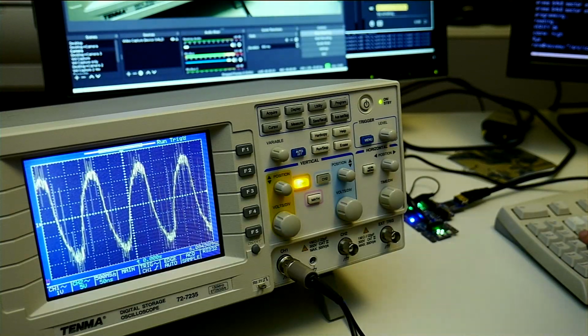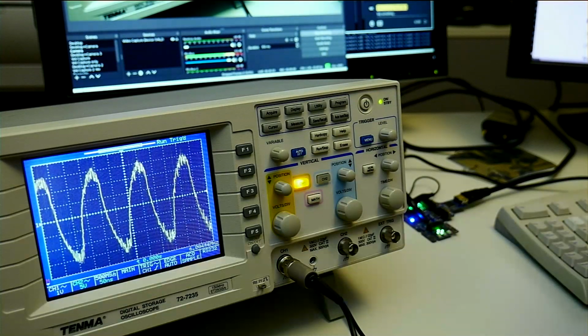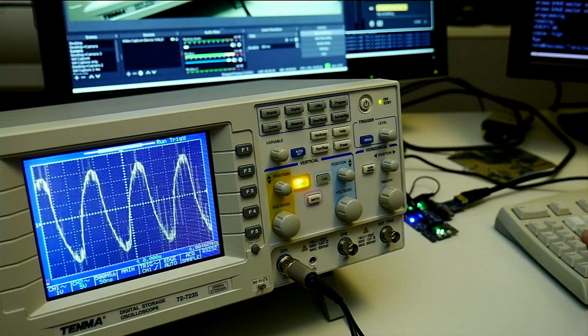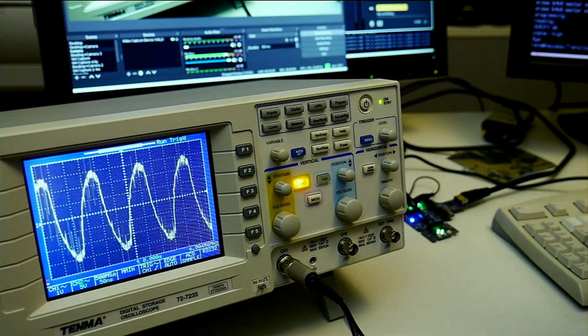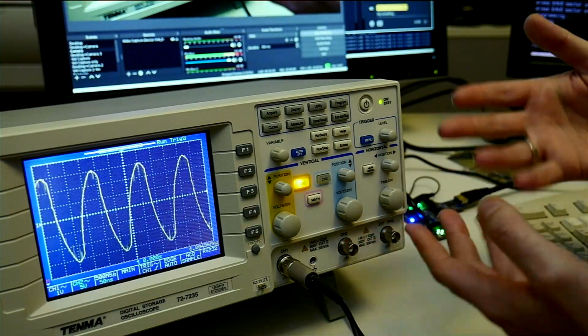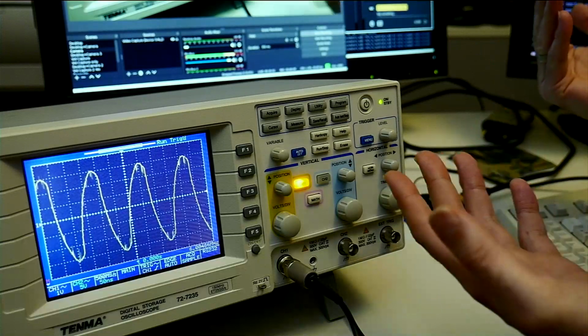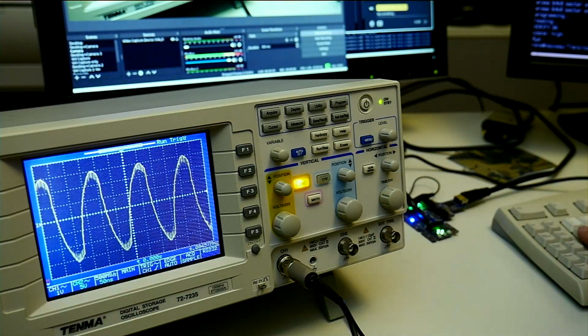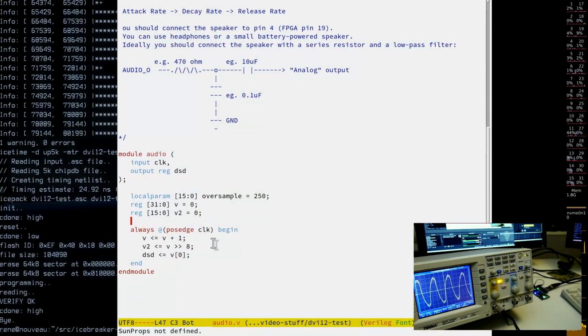So based on this, getting back to what we wanted to do in terms of direct stream digital, we would have some output register, and for each sample, some sample between 0 and 255, for example, to keep it simple for a start. We would not output here this counted clock, obviously, but the value we compute in some form here.